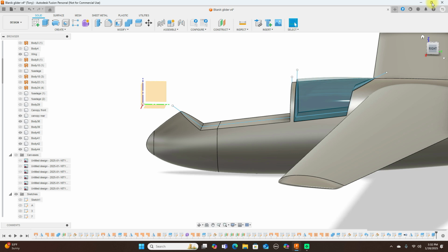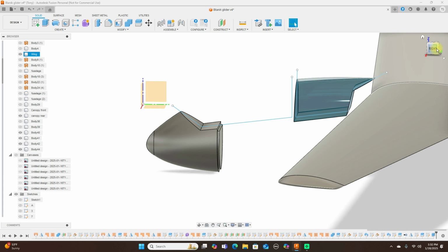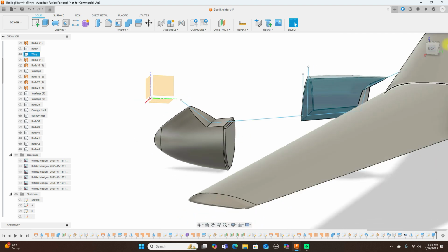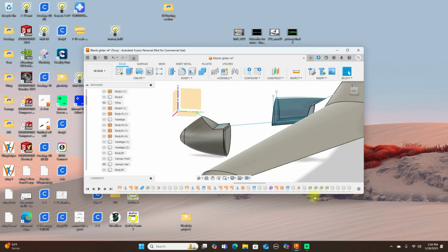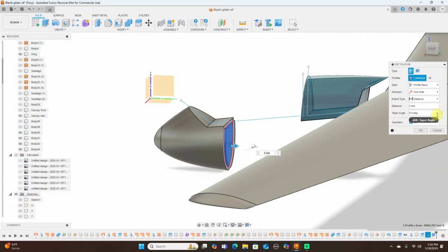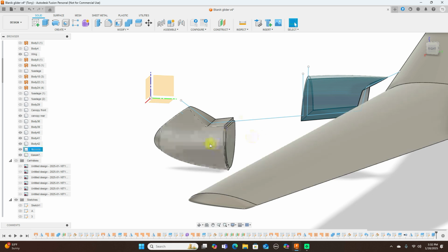It was extrude, okay. What I'm going to do here is, when I extruded this, I set join, but I'm going to make them separate. So I need to go back and find that extrude when I did that. Which is this one. And like this, a new body, and click OK. Now these two should be separate, and they are.